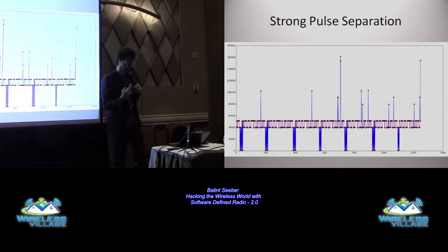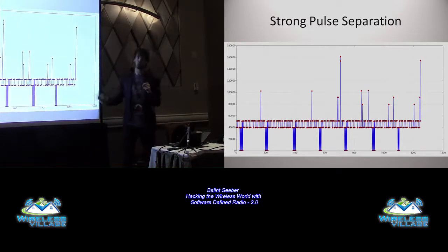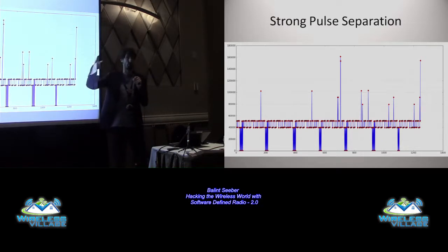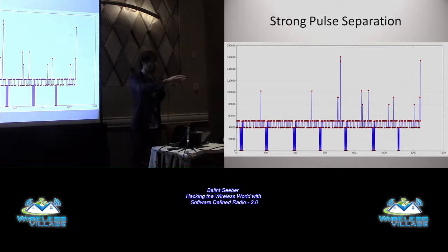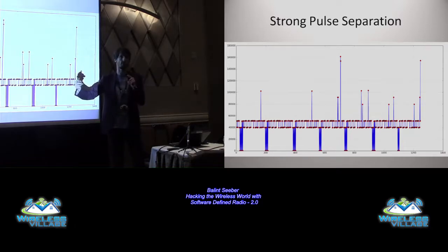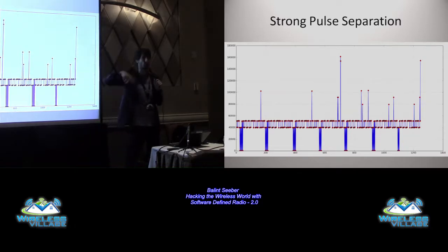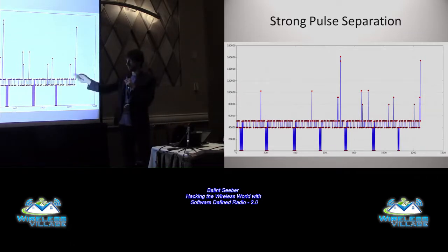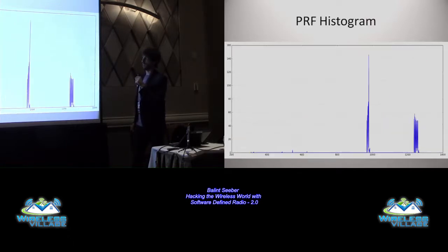I was expecting one. And what this actually shows you is that the radar is operating in this mode called dual PRF. So it's actually switching between two pulse repetition frequencies. It might send out like 10 pulses at one, switch to the other one, and send another like 9 or 10. It's completely random, and it keeps switching back and forth. And it does this to resolve ambiguities. So the system needs to take this into account now as well. You can program that in.